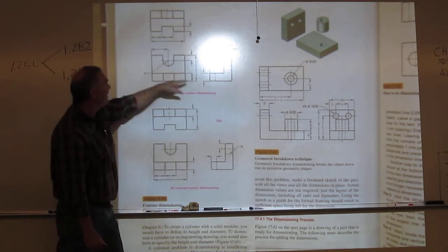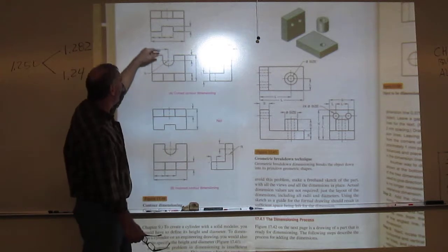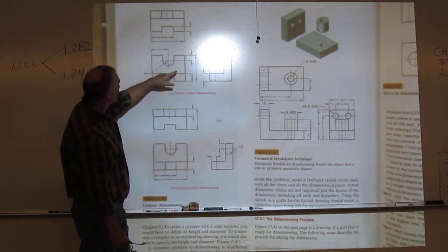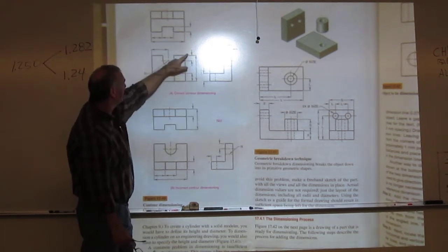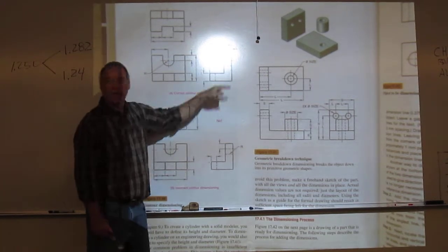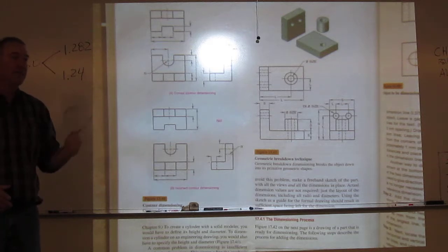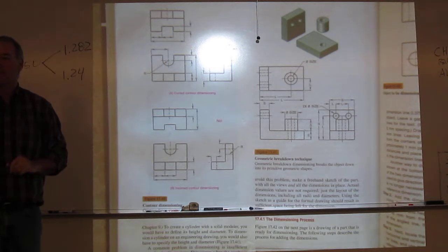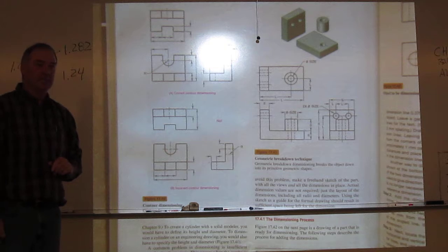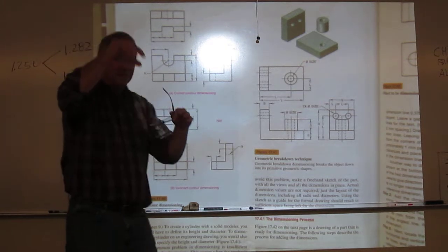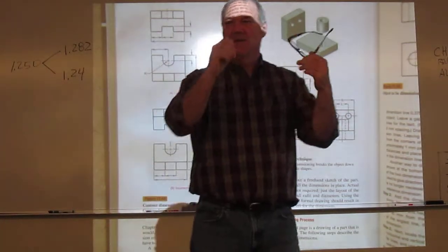I shouldn't take the height and stick it over here where I would have the size, where I've got this location but I don't have this one, because I moved it off somewhere else. Let's put all three dimensions that I need for that slot in the same spot or with the same view. So as they start to construct that slot, they're just looking at one thing.